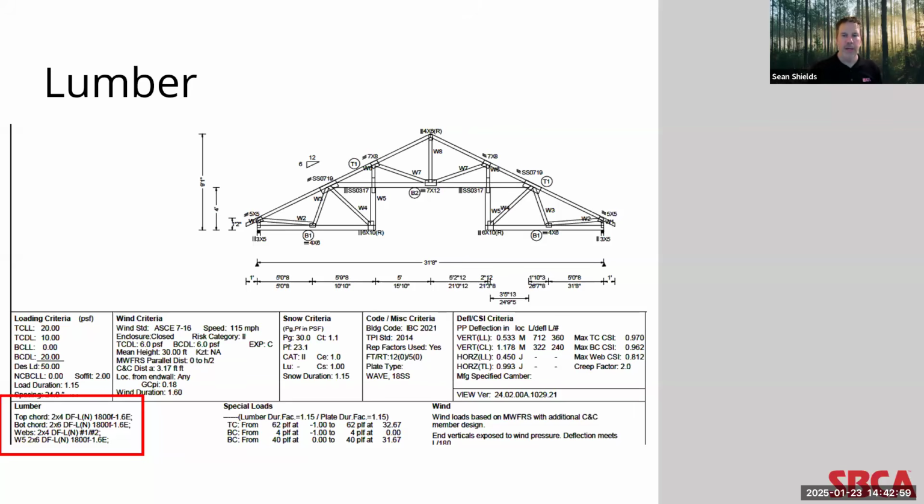As a rule of thumb, the strength properties of visually graded lumber increase as the numbers get smaller. And for MSR graded lumber, typically it has higher strength properties the higher the number it gets, anywhere from 750 to 2850 here in North America.